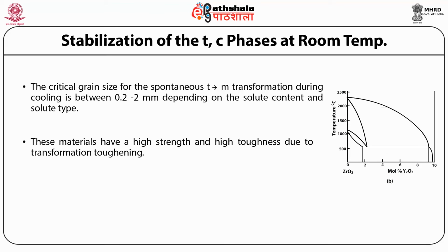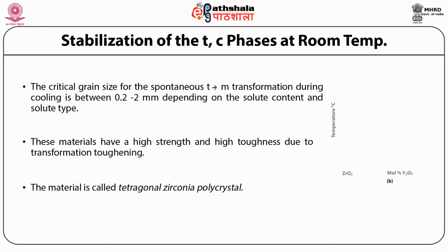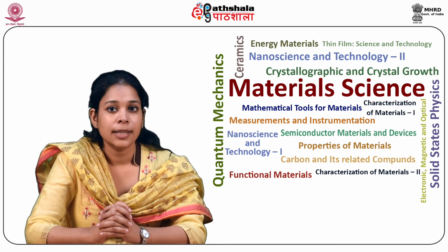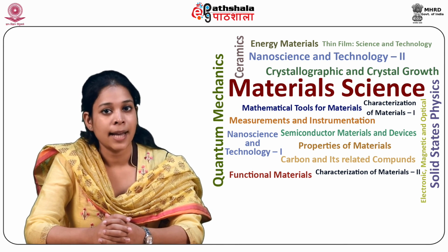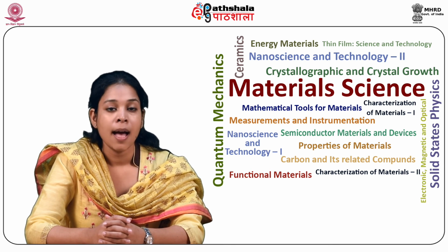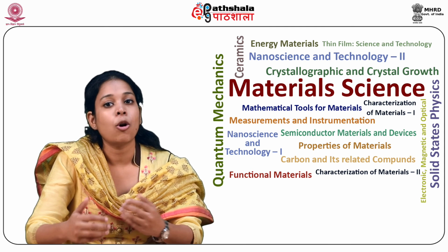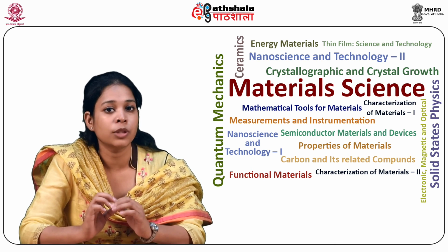For the microstructures of the various types of zirconia, the reader should know that this type is known as tetragonal zirconia polycrystal. The particles of zirconia containing these solutes, that is yttrium oxide, Y2O3, and cerium oxide, CeO2, can also be stabilized in a tetragonal structure at room temperature.